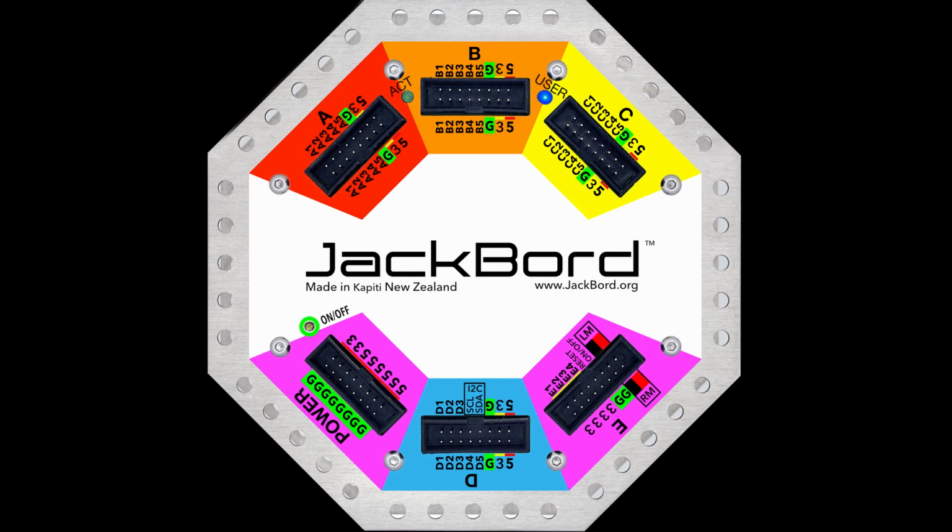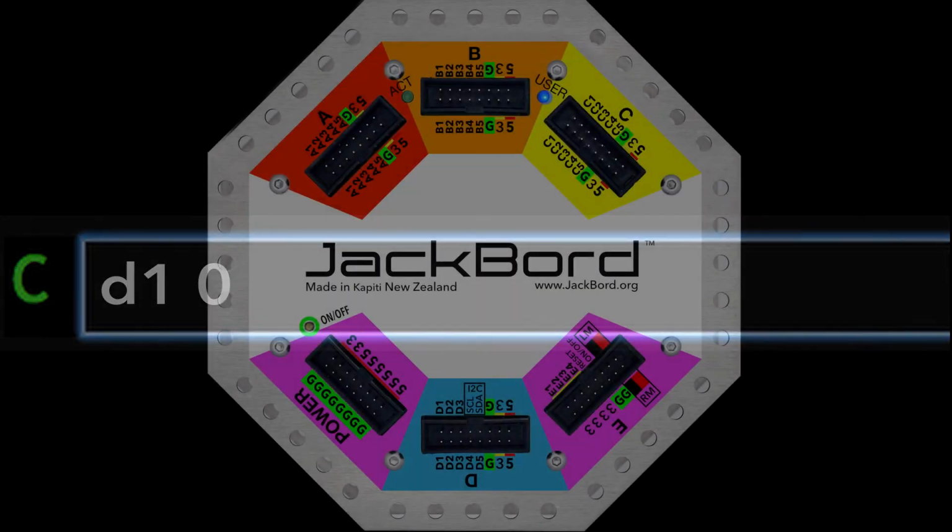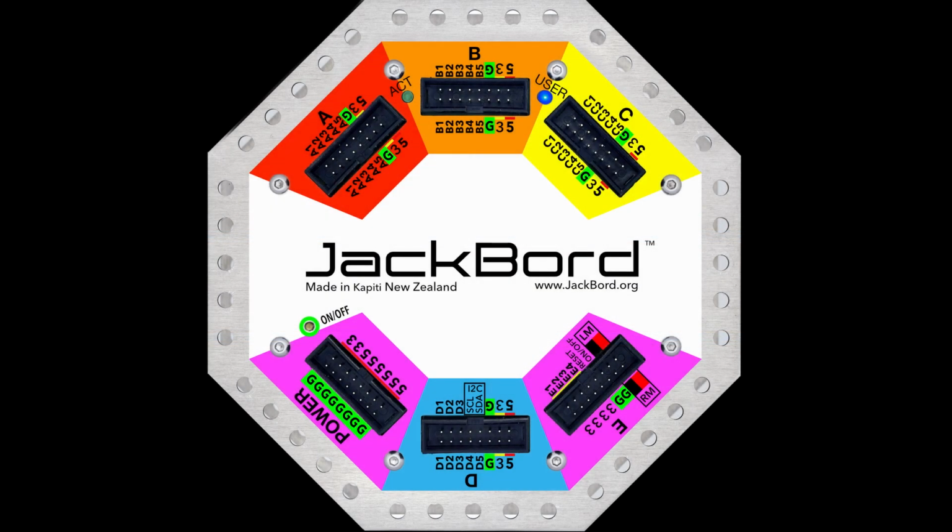To turn it off, you use the D1 space 0 command. Type that at the command prompt and press Enter. You should see the user LED turn off. This method can be used with other ports as well. All you need to do is type in the port's name and follow it by a 1 to turn it on or a 0 to turn it off. So to turn port A3 on, you would type A3 space 1 and press Enter. To turn it off, you would type A3 space 0 and Enter.